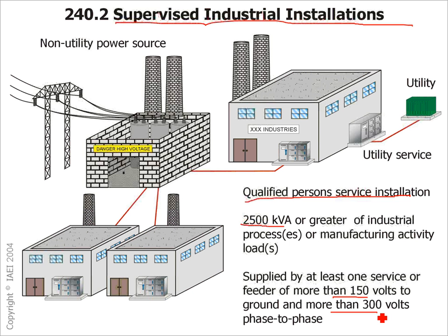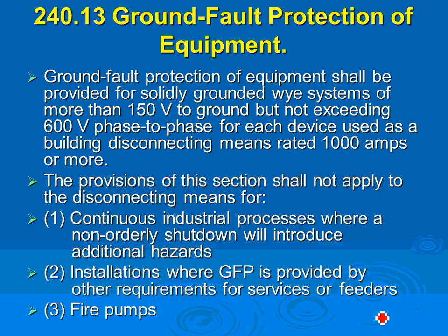That's a lot of power. And with qualified people maintaining it, you can do almost anything you want. They relax the overcurrent protection device requirements. You can do a lot of stuff because, if you can size it, the tap rules become relaxed. This is not open to the public. They have smart people maintaining it, so they relax the rules a little bit for places like this.